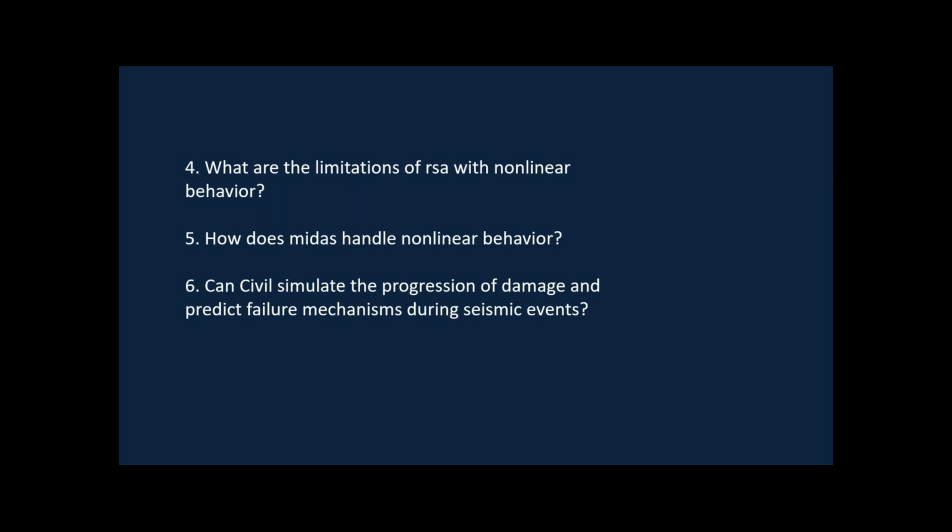Coming to the sixth question, can Civil simulate the progress of damage and predict failure mechanisms during a seismic event? If you mean the progress of damage in terms of crack propagation, the answer is no. The progressive damage or crack propagation cannot be predicted.